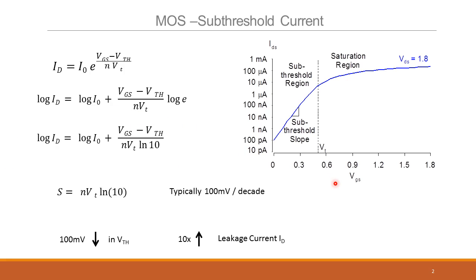So scaling of VT is not aggressively possible, and it is because of this relationship out here. You really do want to have low VT devices so that when it's turned on, you get a lot of drive. But if you reduce VT, your leakage current increases. Of course, only the digital people call this leakage because they really didn't want this current. Analog folks actually tend to, as I said before, make use of this exponential relationship to make some cool circuits.